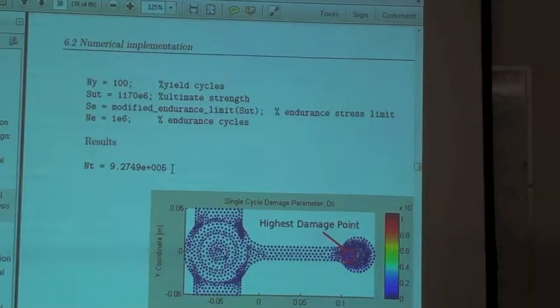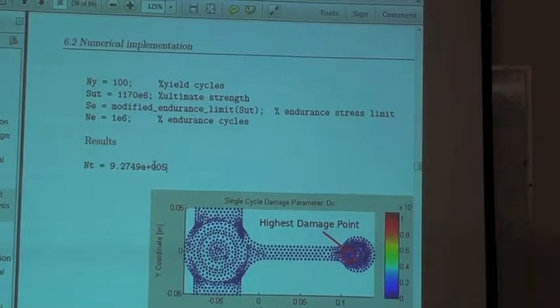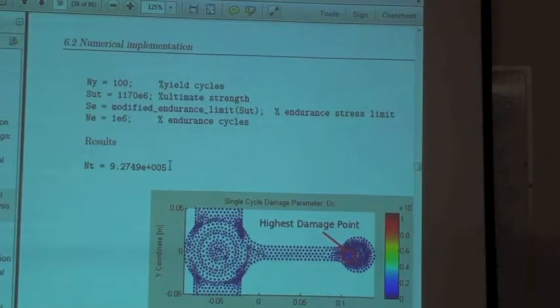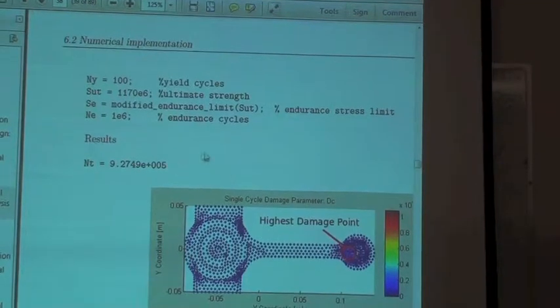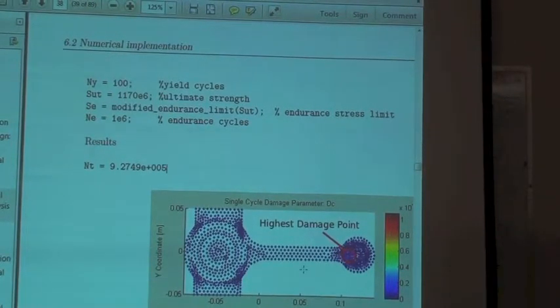Well, for the connecting rod, I think it should be infinite life, but at least they should get 1 billion cycles minimum for the connecting rod. But this is really a good illustration of how we calculate the damage per cycle and how we can control it. In fact, it can help you do optimization. Once you identify the critical points, you can optimize a little bit more. If there's a cost function or penalty function, adding more material will cost more, but at the same time you can improve the lifetime. So there are some trade-off issues here.